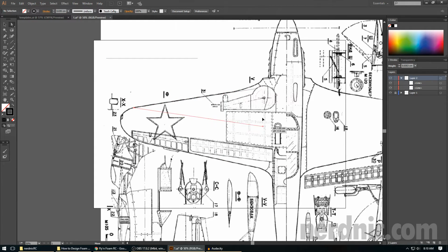And the newer versions of Illustrator actually show you your previous line. So when I have it placed there, if I move it, you can still see where the line was, and it'll lock onto it. If you're wanting to make it longer or whatever, where it turns purple like that, it means it's still locked on to the same degree or angle that you were. So you can make it shorter or longer without changing the angle of the line. That's kind of cool. But yeah, you can see the old reference line of where you were, and then you can make your adjustment.